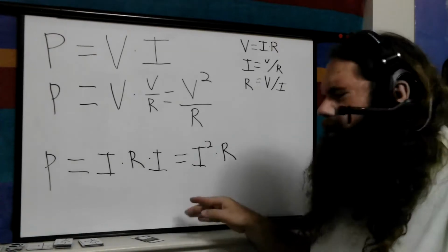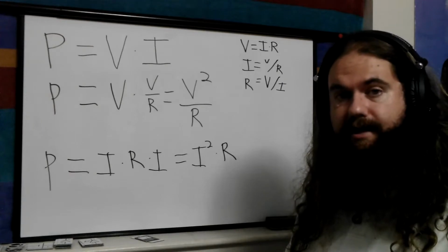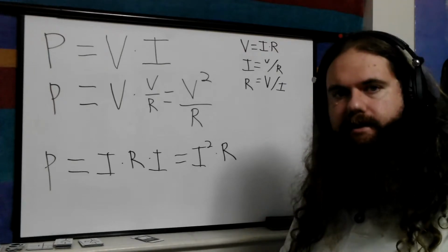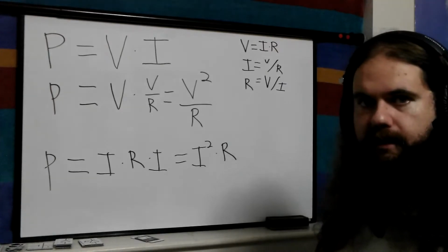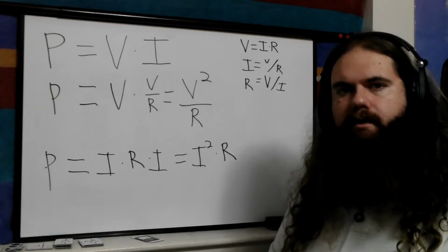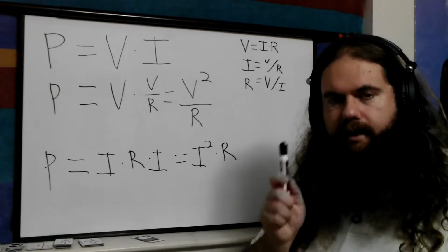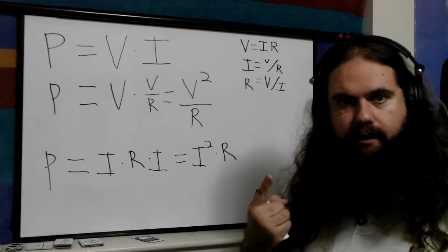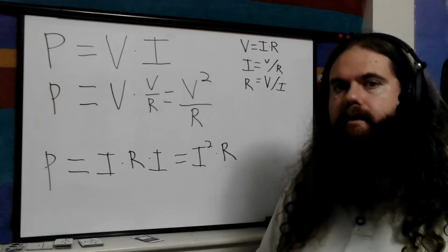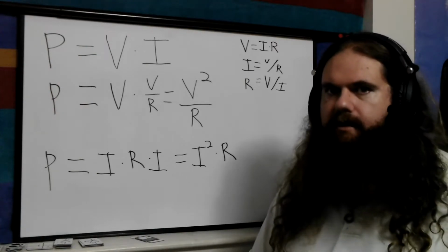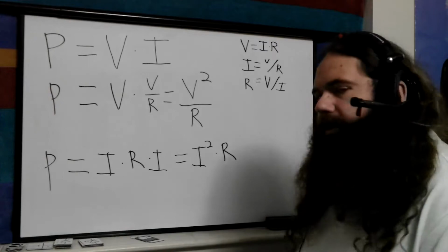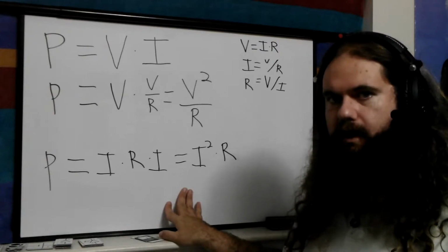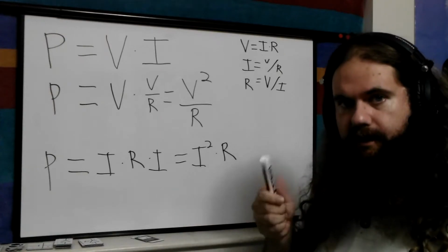Now, one more quick thing. One common thing is to make sure you are not exceeding the power level for a particular component, such as a resistor. The resistors I buy are a very common variety used by hobbyists everywhere: 1/4 watt. They are good quality, but cheap, plentiful. And for low power circuits like messing around with Arduinos and LEDs, it is more than enough, because we are dealing in milliamps. But let's say we have a circuit, and we want to figure out if the resistor is getting too much. So we know the resistance of the resistor.